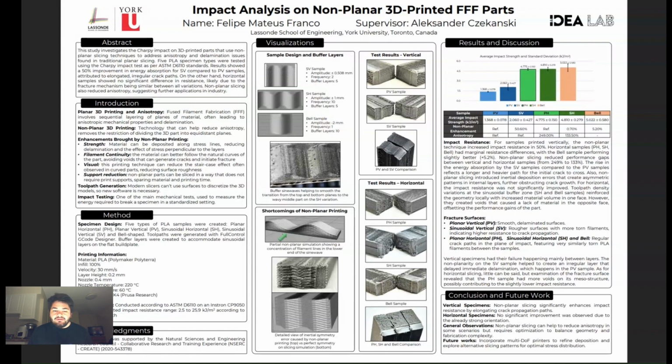For example, usually when parts are printed in a planar way, the build direction, which is the z direction, is weaker than the normal x and y directions, because the material delaminates and the layers detach instead of only withstanding the stresses with the material properties.